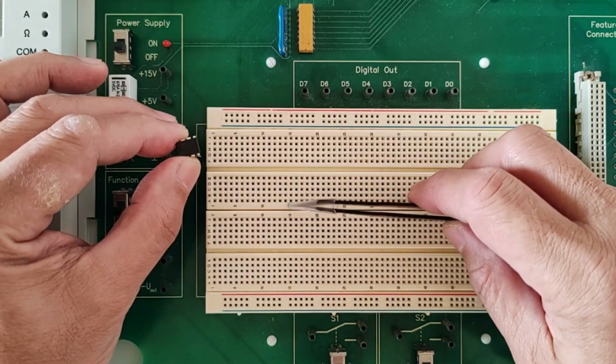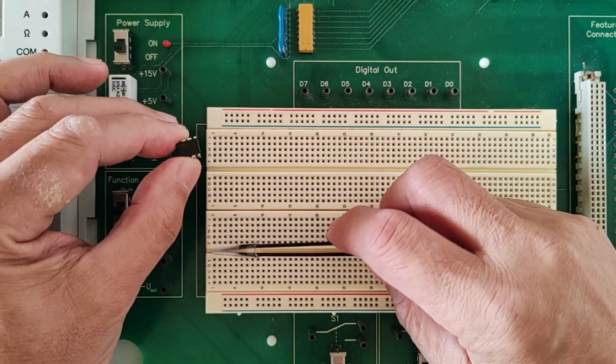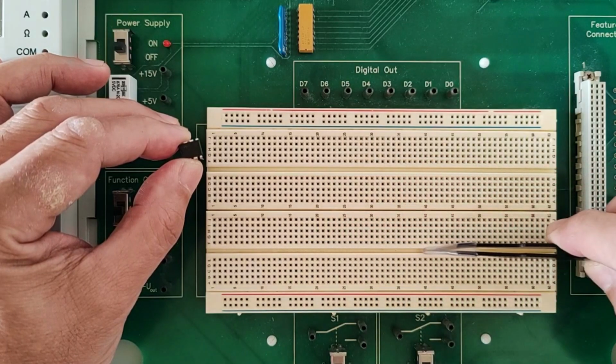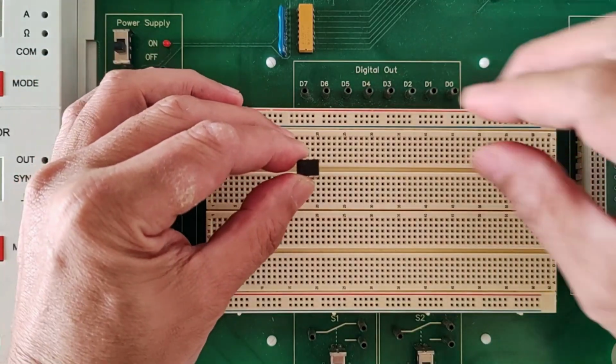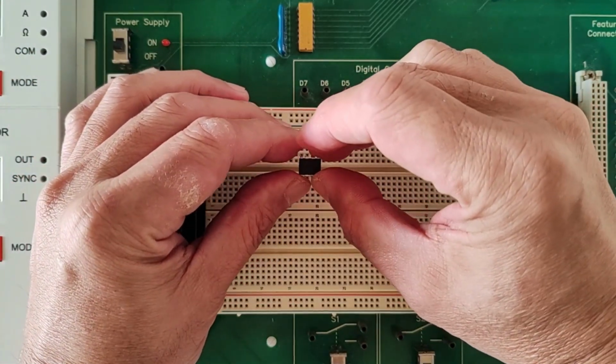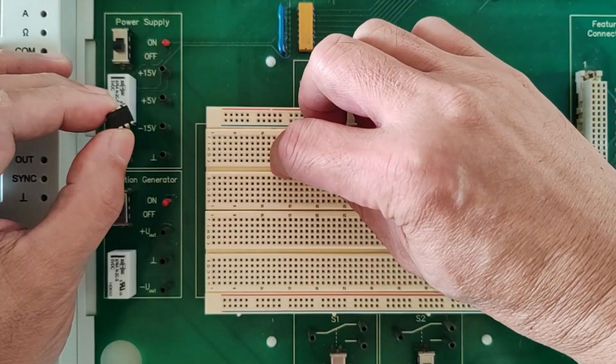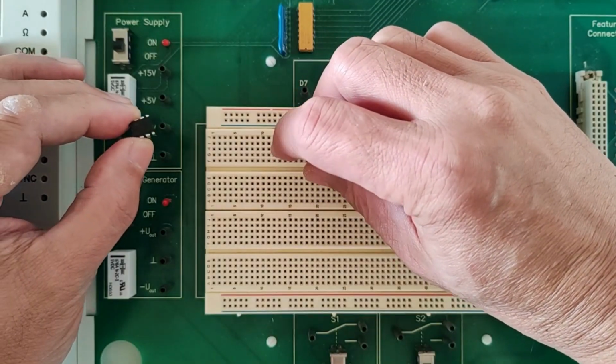Don't use the one in the middle here. There are going to be some problems if you put it there. The IC will surely be loose, okay? So either you put it down here or up there. Try to find the place on the board where the IC would be a snug fit, where it's a little bit difficult for you to pull it, okay?